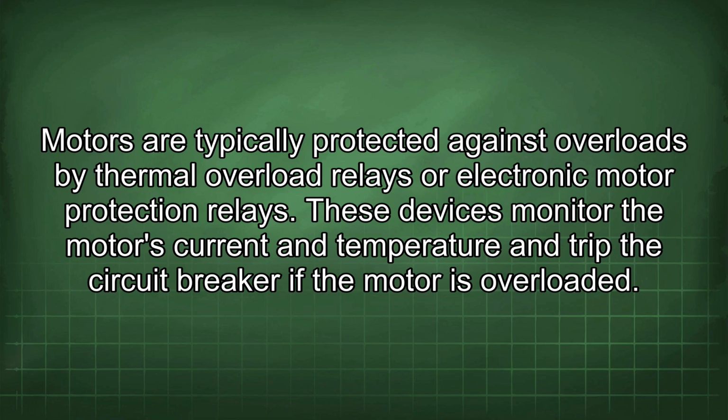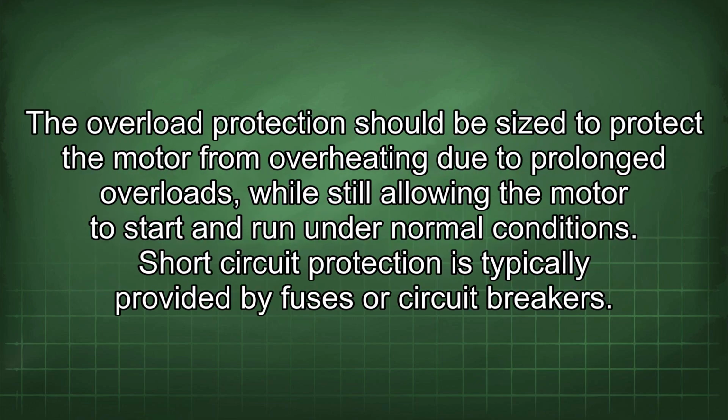These devices monitor the motor's current and temperature and trip the circuit breaker if the motor is overloaded. The overload protection should be sized to protect the motor from overheating due to prolonged overloads, while still allowing the motor to start and run under normal conditions. Short circuit protection is typically provided by fuses or circuit breakers.